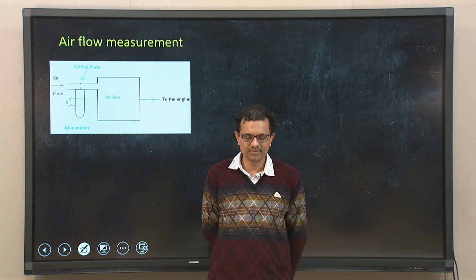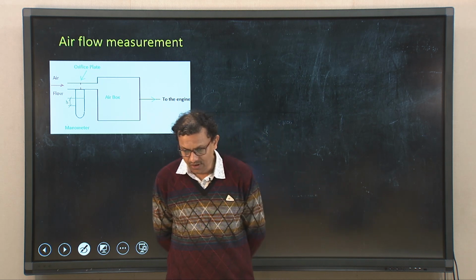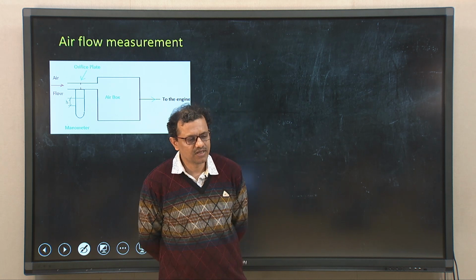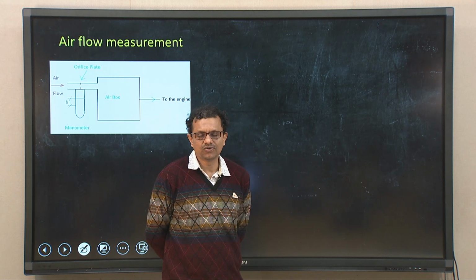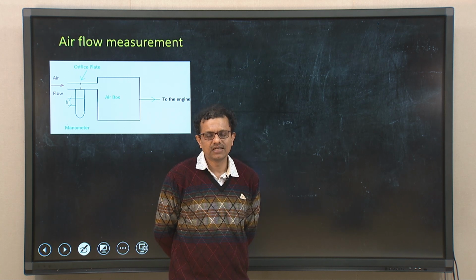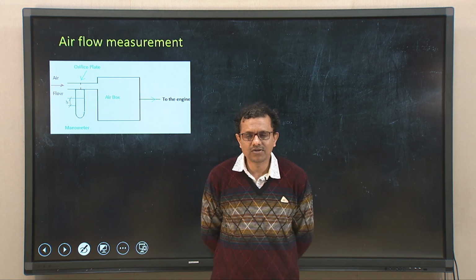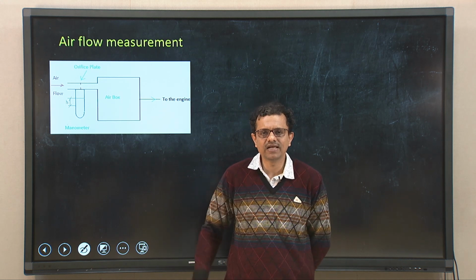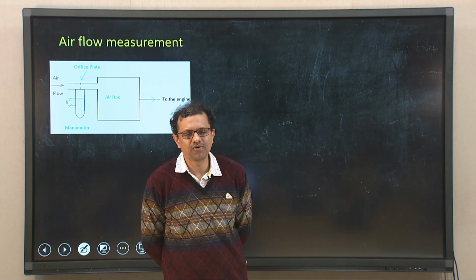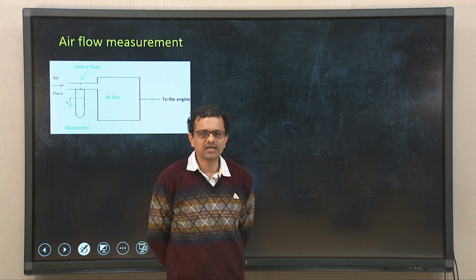Let me repeat once again, actual measurement of air flow is very important essentially to calculate air fuel ratio, but actual measurement of air flow is not so easy, in a sense that the amount of air that we will predict that this engine will take during a certain period of time, that amount of air will reach the engine.